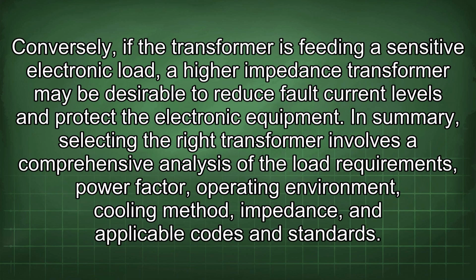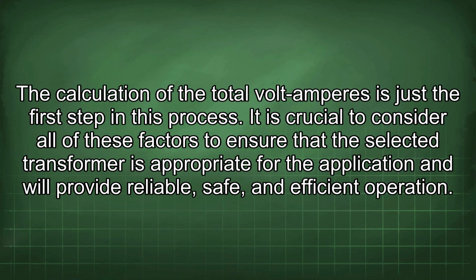Conversely, if the transformer is feeding a sensitive electronic load, a higher impedance transformer may be desirable to reduce fault current levels and protect the electronic equipment. In summary, selecting the right transformer involves a comprehensive analysis of the load requirements, power factor, operating environment, cooling method, impedance, and applicable codes and standards. The calculation of the total volt-amperes is just the first step in this process. It is crucial to consider all of these factors to ensure that the selected transformer is appropriate for the application and will provide reliable, safe, and efficient operation.